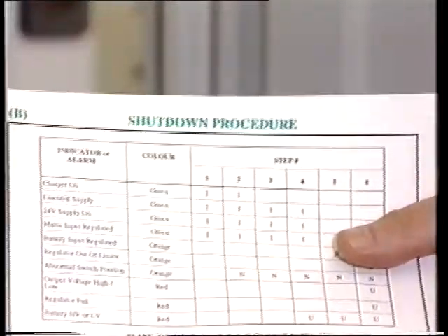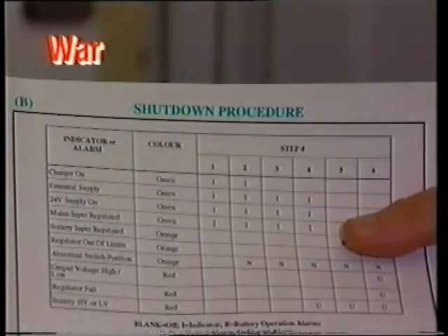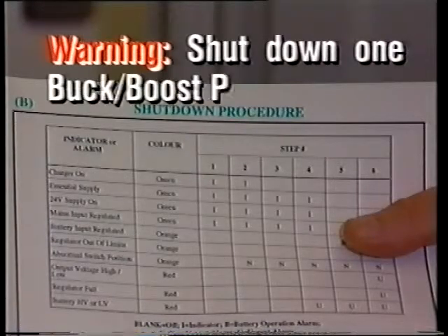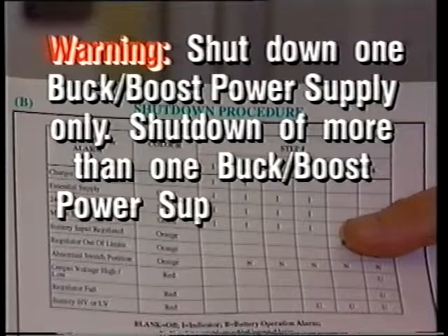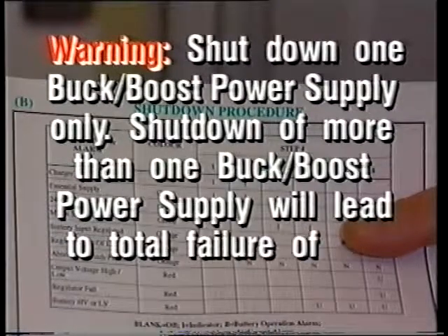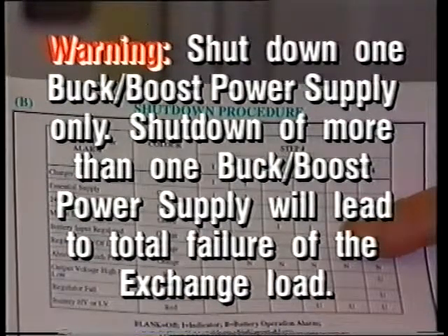If you look at your procedure card, you will find a warning. Shut down one buck boost power supply only. Shutdown of more than one buck boost power supply will lead to total failure of the exchange load. You have been warned.